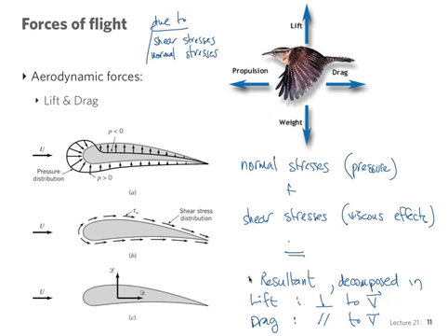I would volunteer that the only way to actually know these is through computational fluid dynamics. If you're able to actually calculate in detail the solution to Navier-Stokes equations around an object and to obtain a measure of all the stresses in every point, then you might be able to integrate those and obtain the forces. But in general, you can see that it would be very difficult to actually know these. But nevertheless, let's move on and see how this would look if we want to make a mathematical description of these forces.